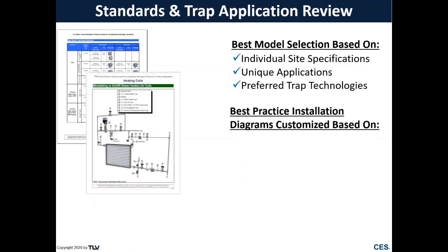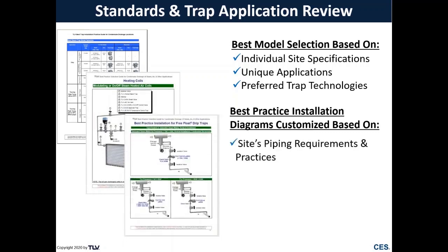So from this, we will help you develop a series of best practice installation diagrams based on your site piping requirements and practices to make sure that every condensate discharge location receives the correct trap as well as has the correct piping requirements in order to make sure that we're avoiding any of these problems that we've talked about.